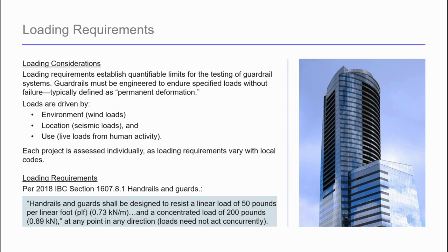Interior railings, supporting primarily the live load, as we discussed, can usually be supported readily by most construction types. However, sometimes you're on a thin stair or a non-structural finish such as stone or terrazzo. You sometimes need to change that or think about that. That might prevent the adequate railing attachment. These issues are usually mitigated by early design coordination.